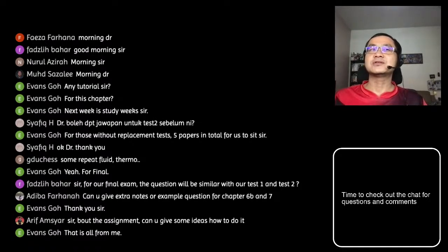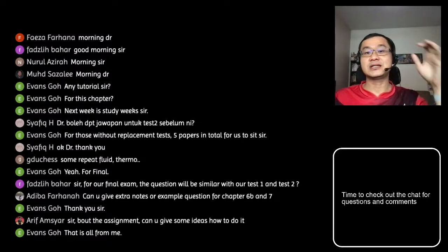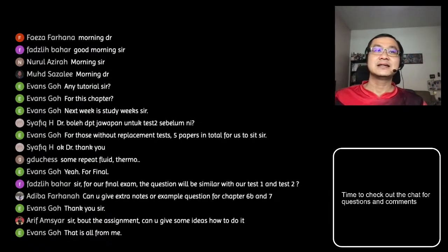As you recall, we don't touch on the PID design. But the PID design is actually just the combination of PI and PD. So you can do the PI first, then using that PI transfer function, you adjust it using a PD. Then you get the PID. Very straightforward. Or if you are keen enough, you can also learn through the examples in the textbook given by Norman Nise.